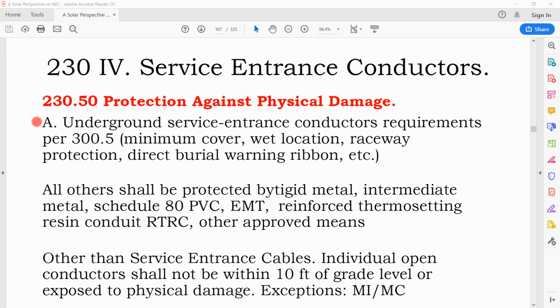What would be smarter for an expandable system is, when you're digging your trench, to put in an empty conduit rather than a full conduit for future use. And so I'm more of a fan of using direct burial rated cable and doing exactly that, just throwing it into the trench and covering it, at which point you put down a warning ribbon. So if people are digging in that area, they're going to cut into the warning ribbon before they cut into your conduit and kind of signal to that trencher, hey, there's something down here.